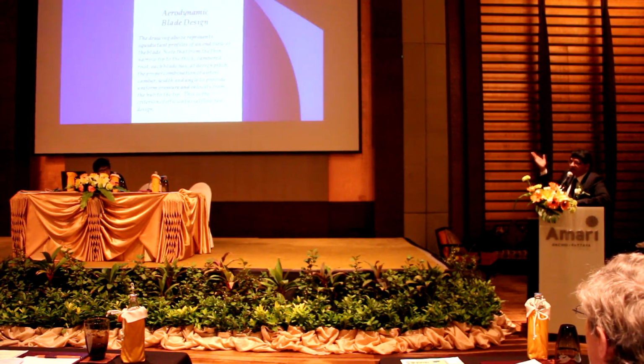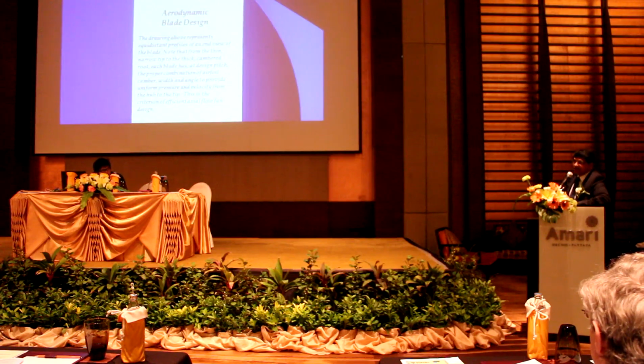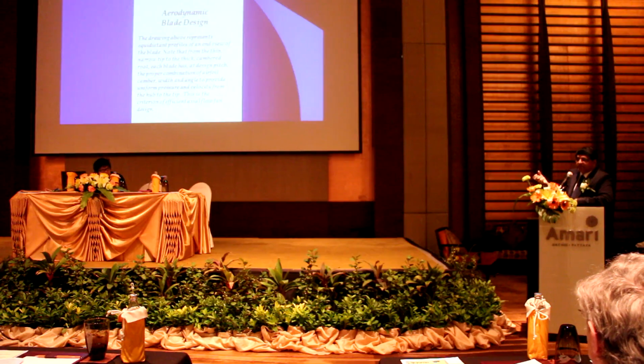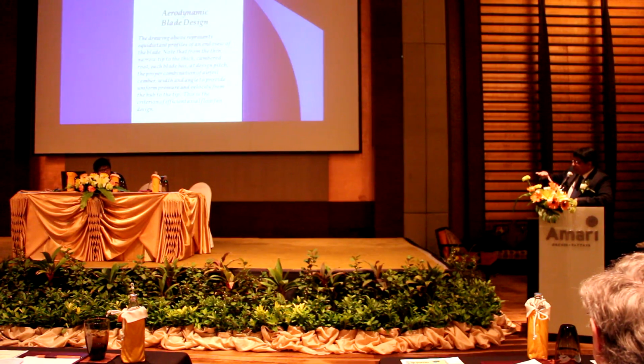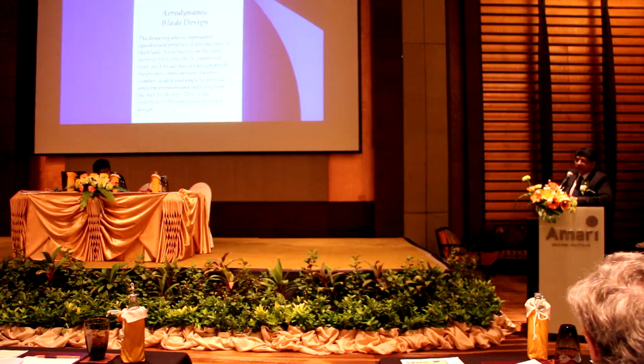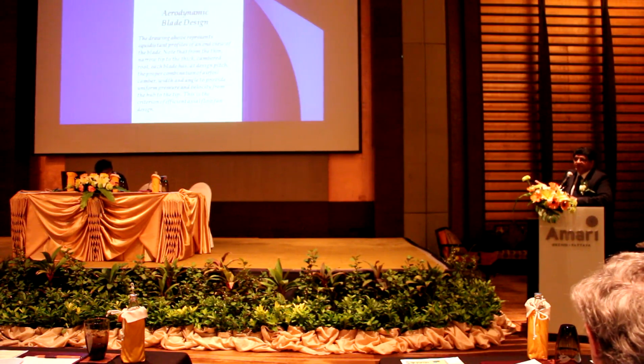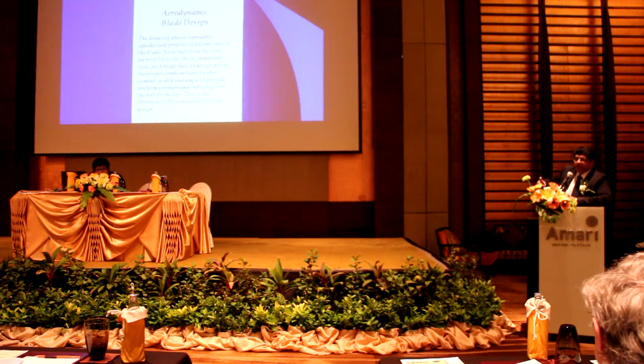The importance that we have been able to get in this kind of aerodynamic design is not possible to achieve in metallic blades, because most of the metallic blades, when you twist them, fixing them to the hub becomes a problem. So these are made with constant chord, because they're trying to overcome the probability of not being able to twist the blade, because the blade fails if you twist the metallic portion, because of its own metallic limitations.